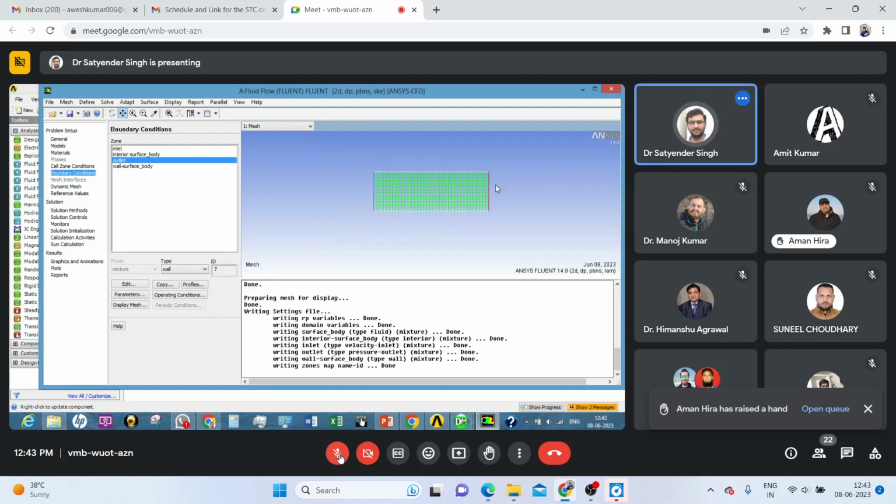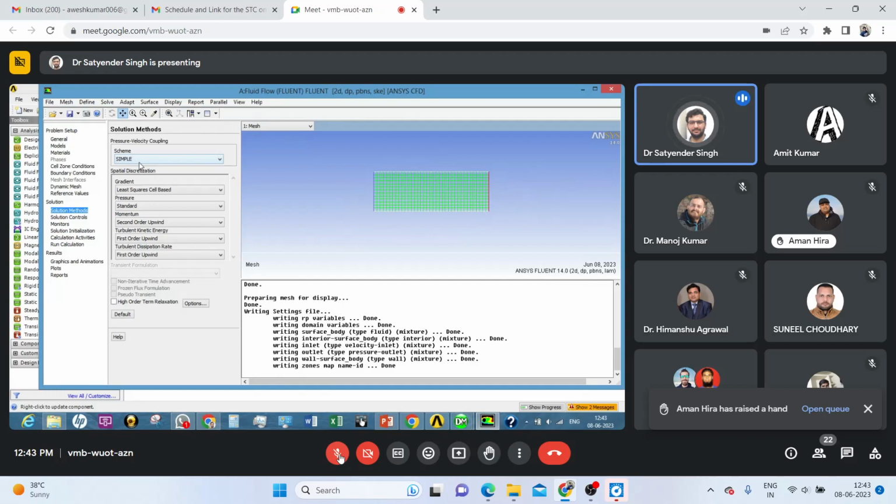Similarly here also, and here we will write the boundary condition p is equal to 0, del u by del x equal to 0, del v by del y equal to 0. So those are the conditions required to solve this problem. Now I'm going to the methods. We are dealing with the pressure velocity coupling method. I'm using the SIMPLE algorithm, which is similar to the semi-explicit method, as we discussed today.